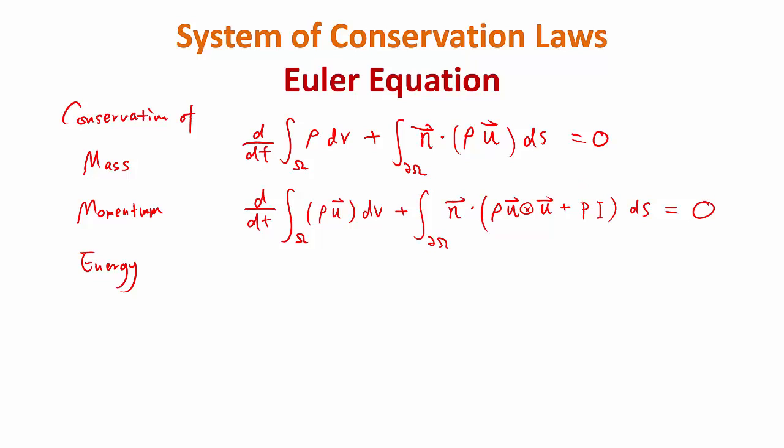What is pressure? Yeah, pressure is a force, but pressure doesn't just depend on rho and rho u. It also depends on how hot the flow is. If you have the same density, same velocity, if you heat the flow, the pressure is going to be higher, right? So you also need the energy equation.